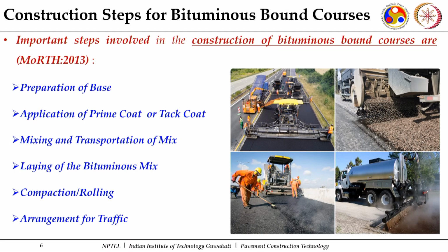Now, what are the important aspects which have to be looked into while going for the construction of bituminous bound courses? One is the preparation of the base where your bituminous bound layer has to come over. So, the existing surface needs to be prepared before you go for the laying of the bituminous bound course. Then depending upon the layer,